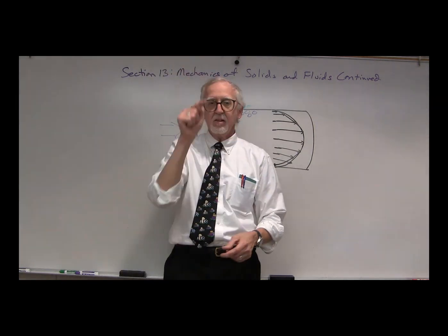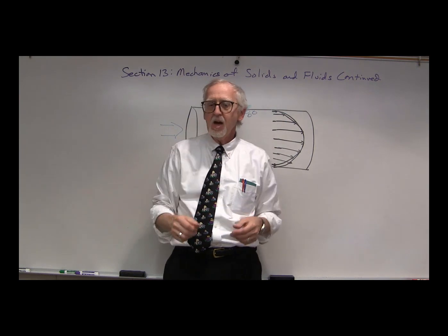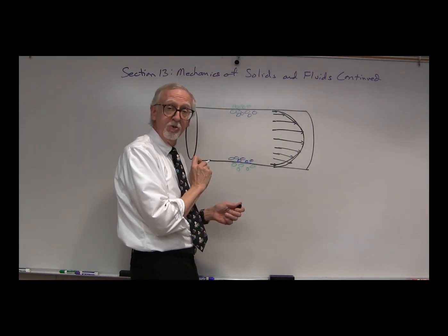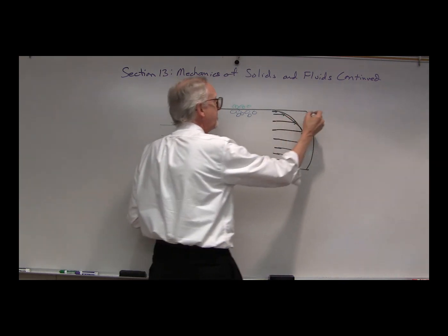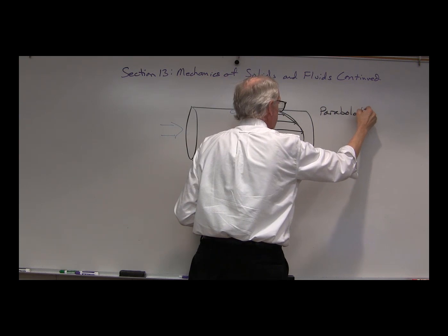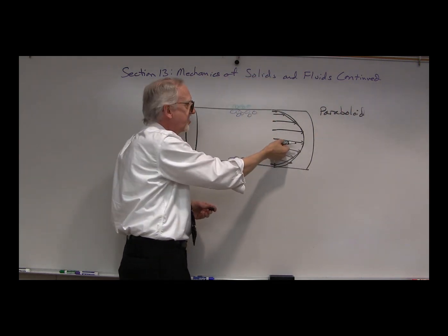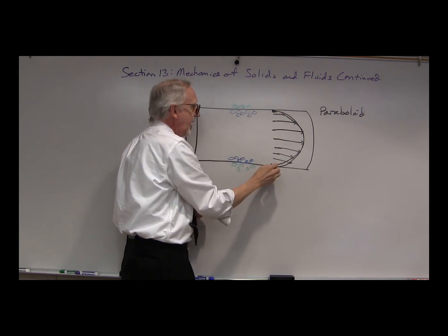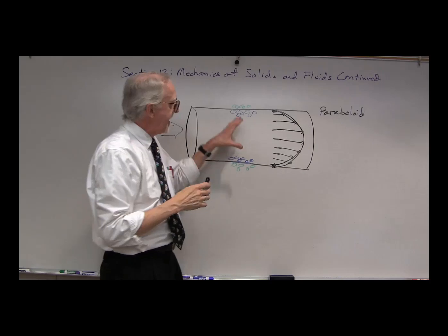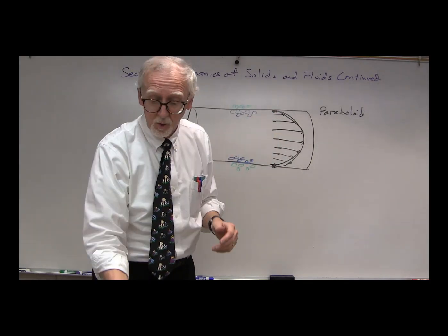It's not just a single line; imagine a rounded cone shape called a paraboloid. So often an approximation used for the velocity in a tube is a paraboloid: highest velocity in the center, and then decreasing to 0 at the very edges of the container. Okay, very good. That is where the viscosity is coming from for the fluid.